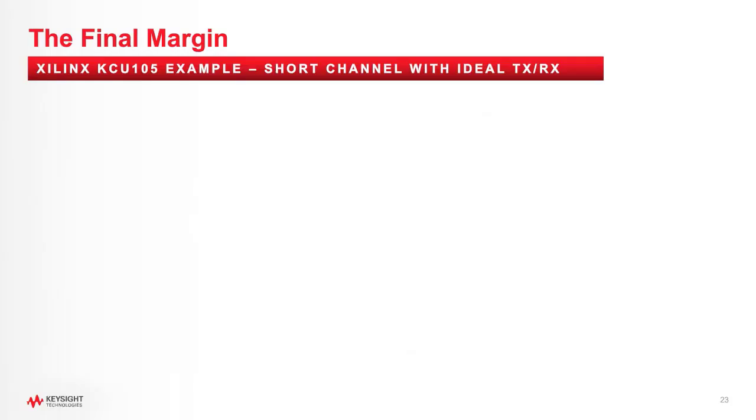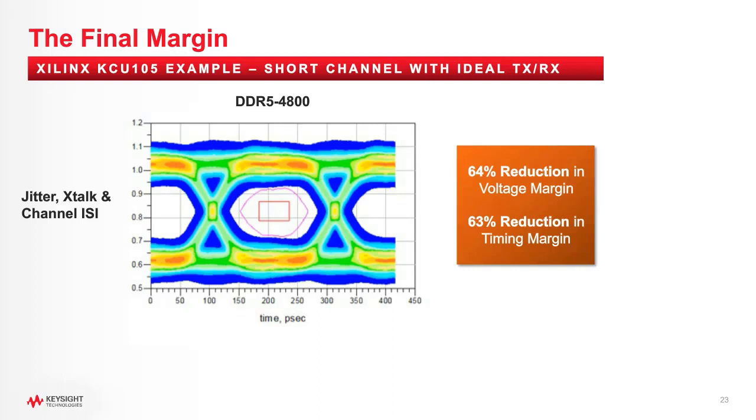So let's put it all together and take a look at both jitter and crosstalk on the channel. Running at the fast speed of 4800, you can see that we get a 64% reduction in voltage margin and nearly exactly the same reduction in timing margin. Now this is with the ideal TX/RX that we've been using, and therefore it has the appropriate rise and fall times for 4800, but it does not include package effects, and it certainly doesn't include any of the other nonlinearities you might find in a standard voltage versus time waveform of an IBIS model.